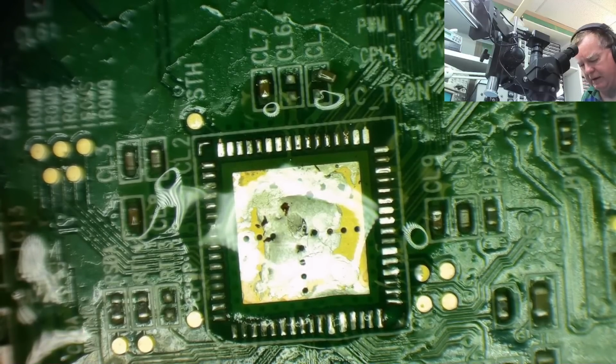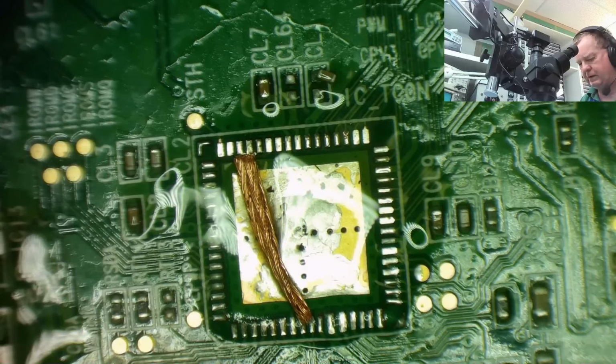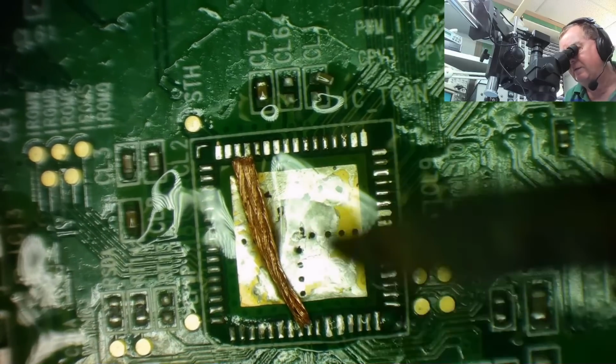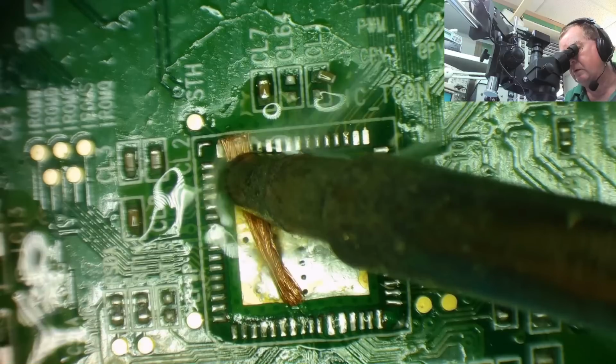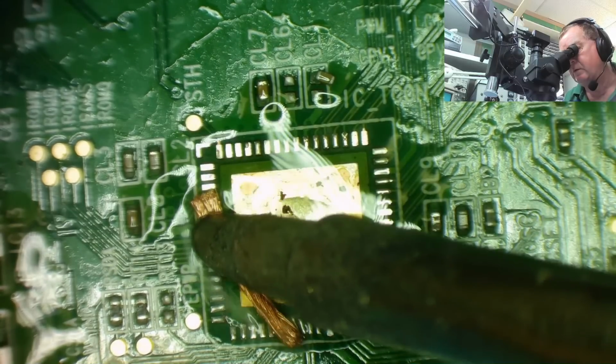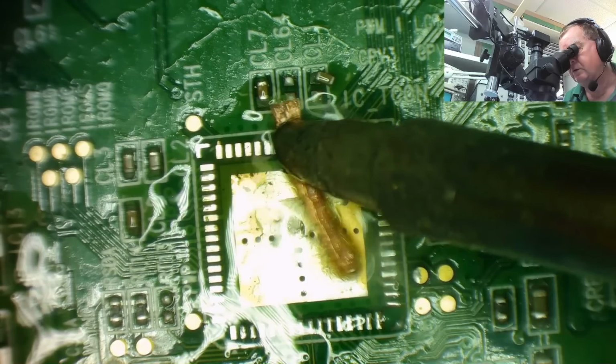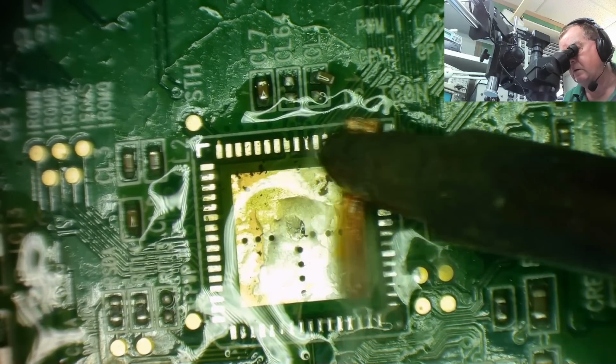Although this braid being thinner than the other stuff I use for the BGAs, that's not normally such a problem with heat being sunk back up into the braid. Let's see if this will work. The thick stuff, you definitely have to cut a little chunk, otherwise it won't work. Yeah, that was working. That's nice. Look at that. Should have done that in the first place, it's so much easier.